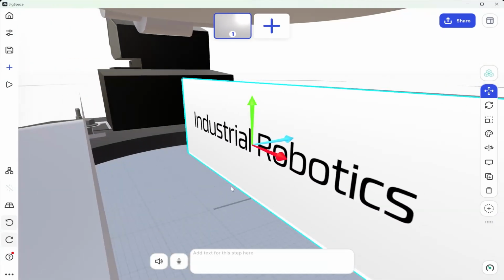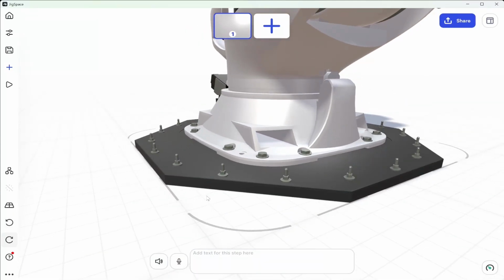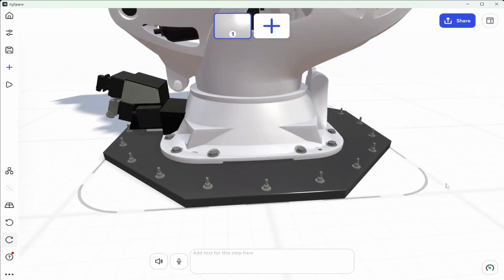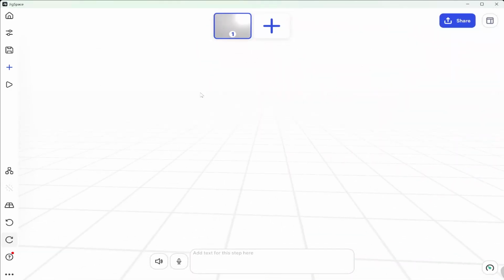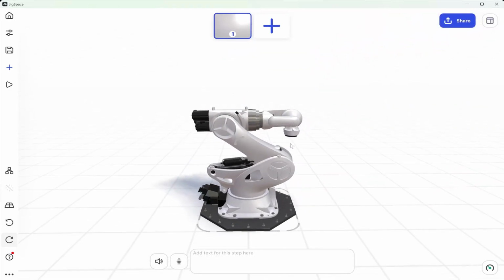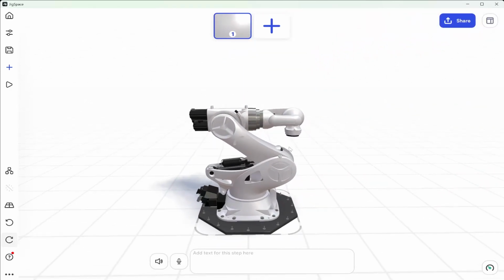Now this image is significantly smaller than the 3D model we have in our scene. So to quickly realign your current view, you just need to double click on the background. And that's going to reposition you so that you're viewing the center point of that world. Now I also recommend getting a side view and then pressing the space bar, click and drag with the left mouse control just to grab yourself and sort of pull that camera aside.